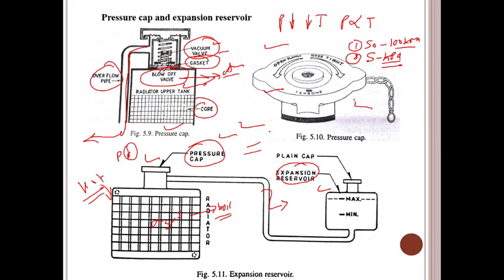Second, air does not enter the cooling system. With this arrangement, corrosion of the cooling jackets and passages and deterioration of the antifreeze is reduced appreciably, and a relatively smaller upper tank may be used with the radiators. So this is the very simple explanation of the radiator, guys.